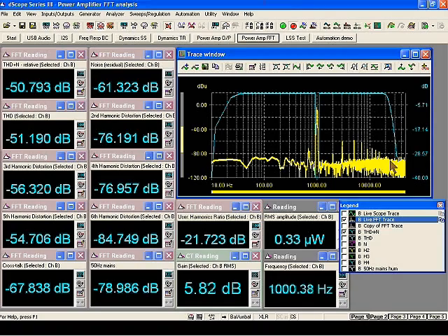And for example, when we want to analyse noise, we can't simply read off the point at which this noise floor here intersects the y-axis, because that is not the noise floor of the system that we're measuring. Each of these data points represents a noise energy at a particular range of frequencies, and we need to integrate all of them if we want to analyse noise. So whilst this is useful information in the FFT, it doesn't give us precise numerical data, and that's the kind of thing that we're looking for when we're analysing closely the performance of something like a power amplifier.